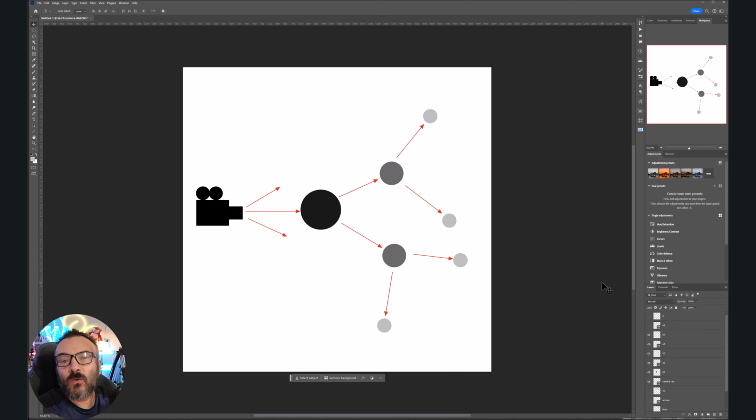But you know what? It can go on so many times. After some time, the application needs to say, okay, right here is the cut line. For example, we render only 3 times in this case, and after this we just stop rendering. We ignore all values, everything. But if you still have a value, if you still have energy, or the brightness, let's say in this case brightness, has not dissipated to 0, then certainly you cut off and you have gray, and certainly you have a black dot. So this would create the grain.